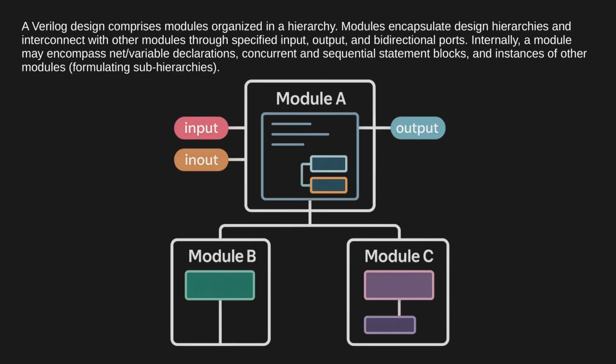A Verilog design comprises modules organized in a hierarchy. Modules encapsulate design hierarchies and interconnect with other modules through specified input, output, and bidirectional ports. Internally, a module may encompass net variable declarations, concurrent and sequential statement blocks, and instances of other modules, formulating subhierarchies.